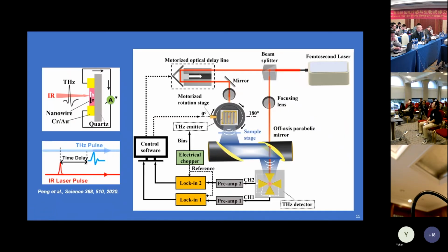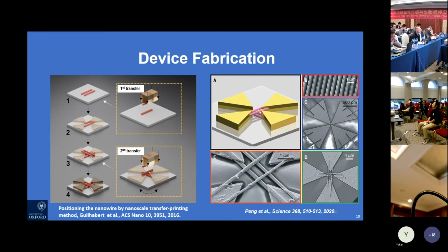On the next slide, here is this nanowire detector. Let me talk about some details of it. As you can see, the number of nanowires in each detection channel can be manipulated, and here I choose two, because I just want to improve the signal size in my detection channel. The total dimension of my nanowire detector is around 2 millimeters by 2 millimeters, and the gap size is around 4 micrometers here.